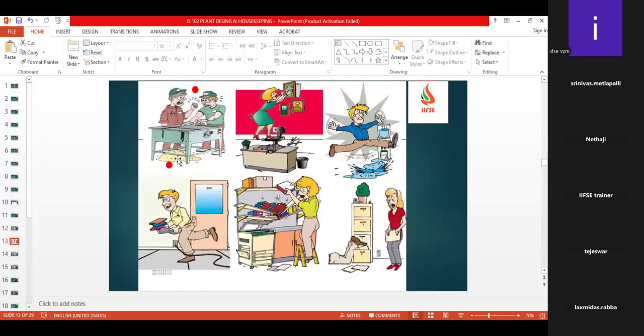Guardrail not available. Yes, good observation. He is not using the PPE. Even the operator is also not using the PPE. And we don't know whether this machine has any sensor. Basically, these kinds of equipment will have a sensor. In case any sensitive material touches the blade, it automatically goes down. Okay, these are the different types of hazards we could see from the first workplace.